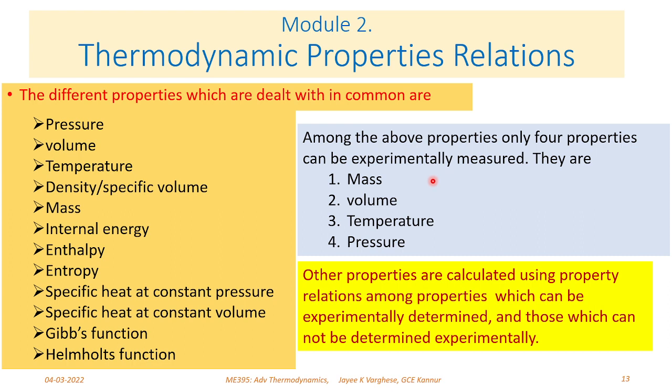Then the volume flow rate and the density of the material are to be known for us to design or size the different parts, like the diameter of the pipeline, which is decided by the volume flow rate and the maximum velocity at which it can be passed. Based on this, we need to design the pipeline.